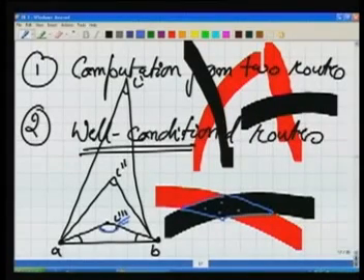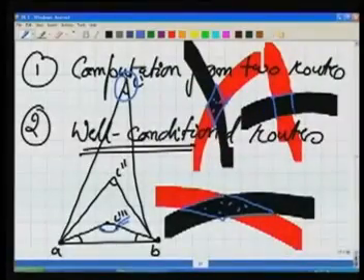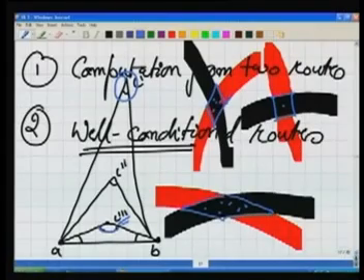It could be anywhere in between. Similarly, over here also the uncertainty is large if the angle is very small. You can do it graphically. But if the arcs intersect at 90 degree, the uncertainty is limited to only this particular thing.